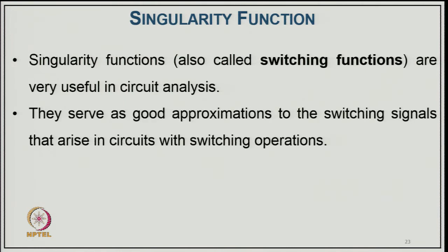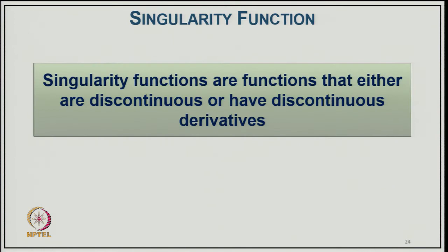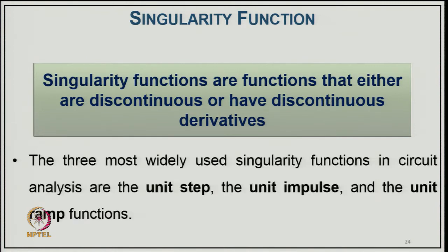For example, they serve as a good approximation to the switching signals that arise in circuits with switching operations, and a basic understanding of singularity functions helps us to make sense of the response of a first order circuit to a sudden application of an independent DC voltage source or current source for these RC and RL circuits. Singularity functions are functions that either are discontinuous or have discontinuous derivatives.